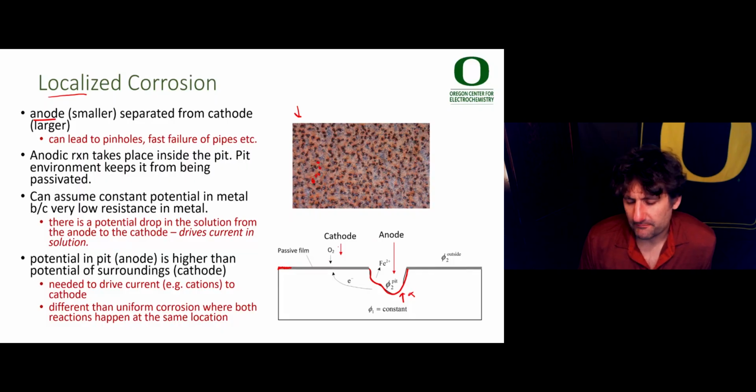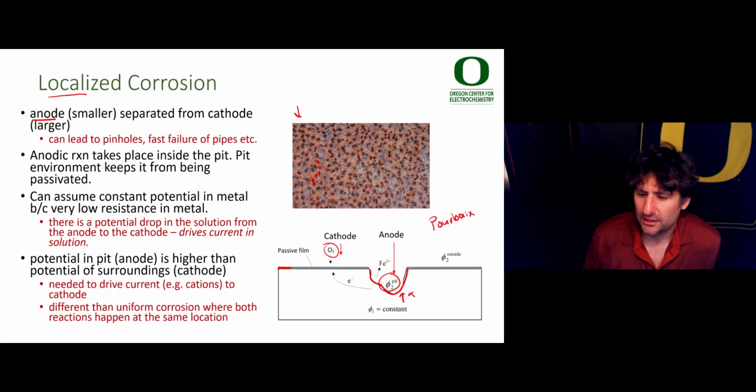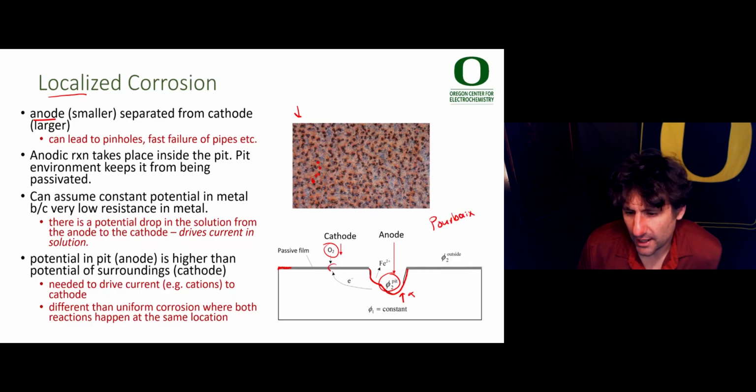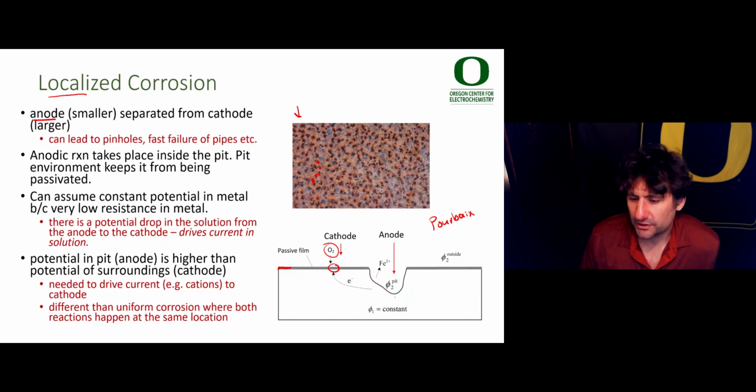So if you think about what the balanced chemical reactions are for these different processes, and you think about the Pourbaix diagram, the potential-pH diagram for iron, you might be able to predict why a passive film might form here and not there. So why corrosion would continue in the pit, even though there's a large area external to the pit over which it in principle could occur.